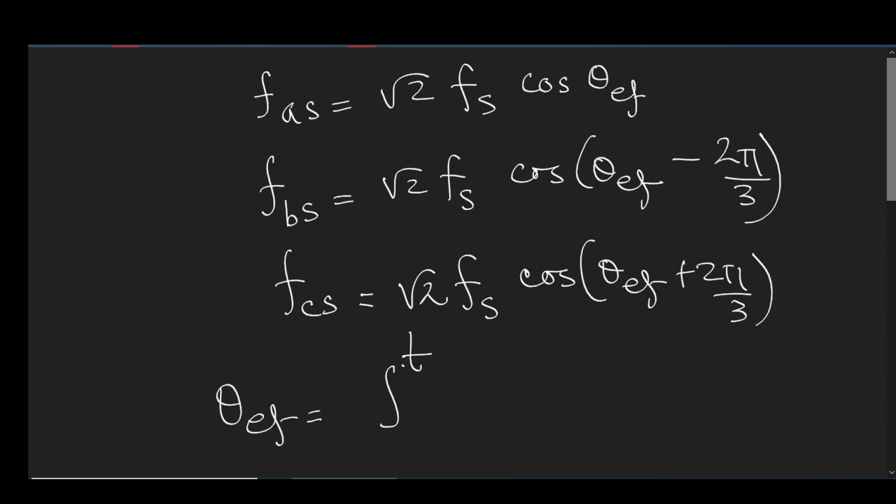The voltage, if it is balanced, which you are going to apply on that three-phase circuit, that is VB is already displaced from VA by an angle of 120 degree. Similarly, VC is displaced from VB by an angle of 120 degree. So what it indicates is that the current will also maintain the same phasor relationship. But in transient, they will change in magnitude, but in steady state, the magnitude will be constant.